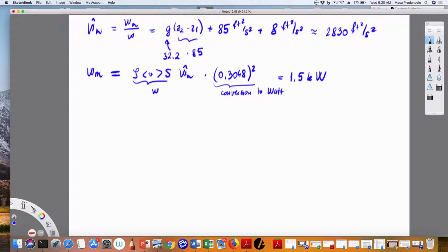If you have a porous medium and you have an impulse to use Darcy's law, still check the Reynolds number. Double check that Darcy's law is actually applicable. If it's not, then you have to go to the Ergun equation and add those velocity terms that have velocity squared in there. Because those inertial terms become important if you have higher Reynolds numbers.